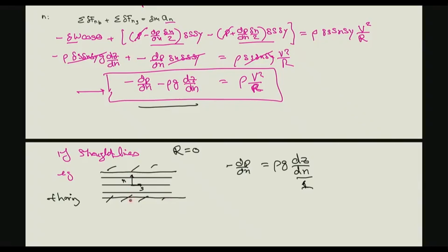Assume that there is no variation of pressure across the pipe. So you're actually measuring the pressure at a particular location, or the pressure difference between, for example, if you drill a hole here and then put a U-tube manometer, and this is open to the atmosphere, then you could measure the local gauge pressure.